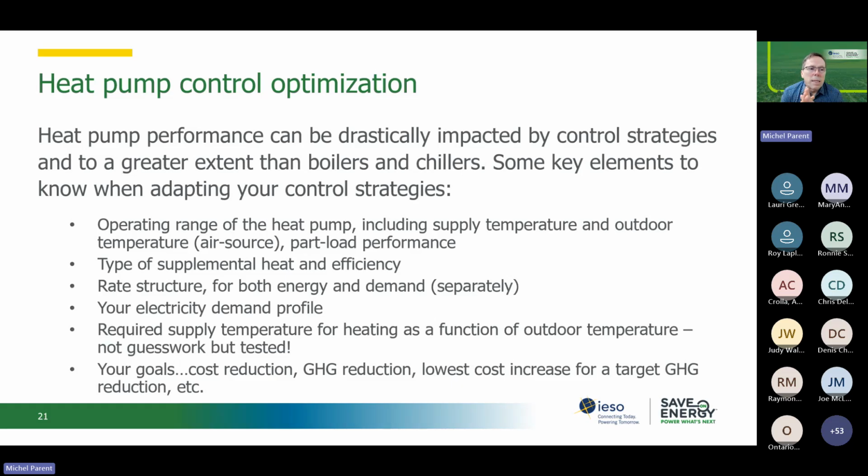First of all is what is the operating range of that heat pump. So until when is it worth running that heat pump? You could decide to follow the manufacturer's recommendation. That means basically leave it to the OEM controller. What is way better is to know what is the heat pump capacity and what is the COP at a given temperature. There will be a point where, because of the energy rate, if you've got supplemental heating, you are better off not using your heat pump and using your supplemental on a cost basis.